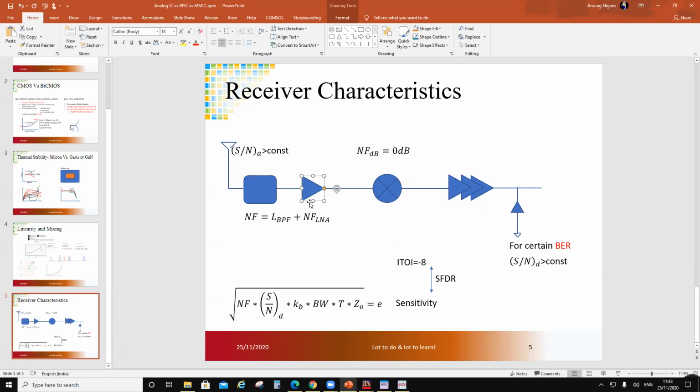So in radars, it's highly likely that you won't have a LNA. You would directly have a mixer for the dynamic range. Okay, so it's just not the thermal noise. It's basically whatever it picks up here. This is the best scenario. But whatever picks up here, if it is stronger than the thermal noise, then you will assume that over here instead of this. Okay. Now, having said that, in any communication system, there are going to be blockers.